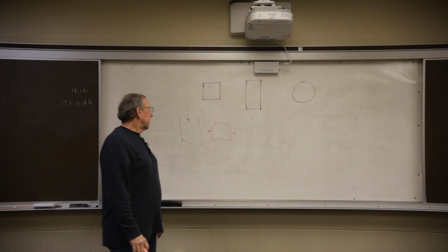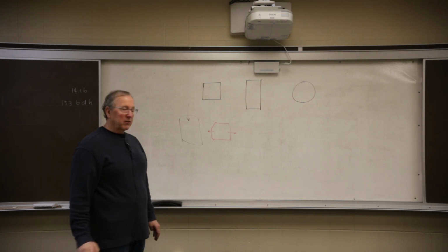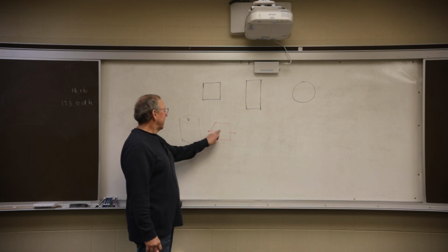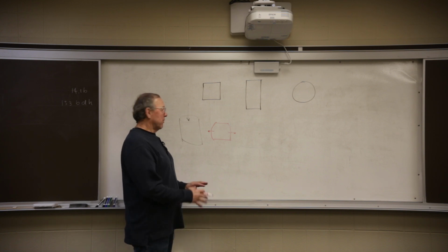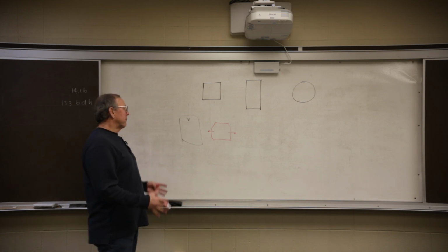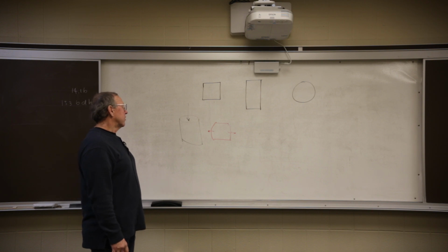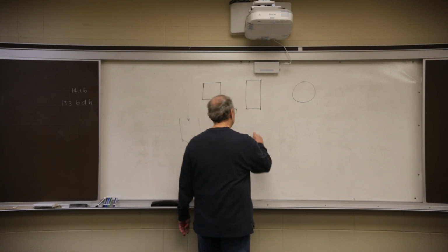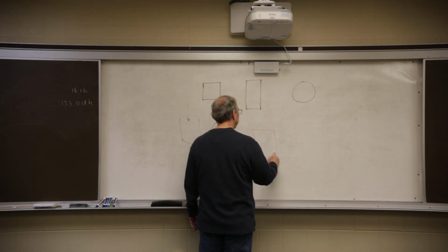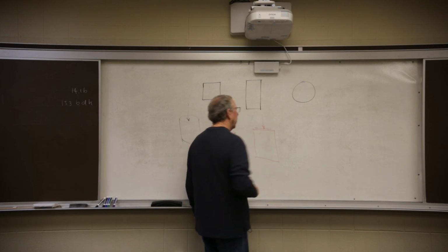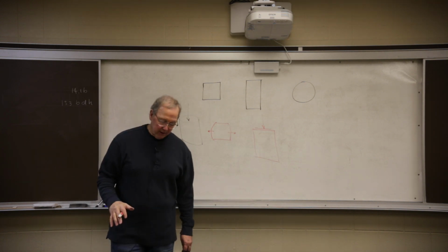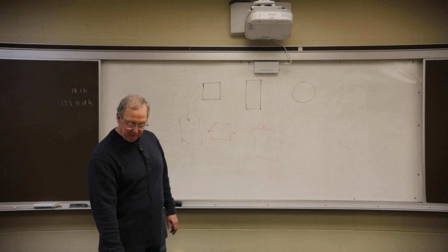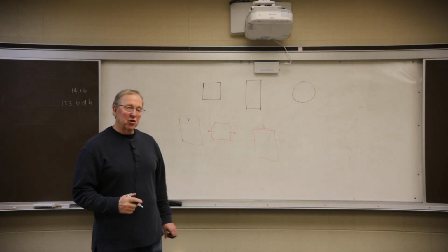And that particular shape then has 2 components. It has a component that's associated with concrete and steel, and it's a lateral movement. So I'm trying to keep it from pushing out. And of course, the steel holds it together. And then the last one is shear. Those of you who have been in the materials lab and put a concrete cylinder in a compression test probably didn't realize what was happening, but your specimen probably failed under this condition, which is shear.